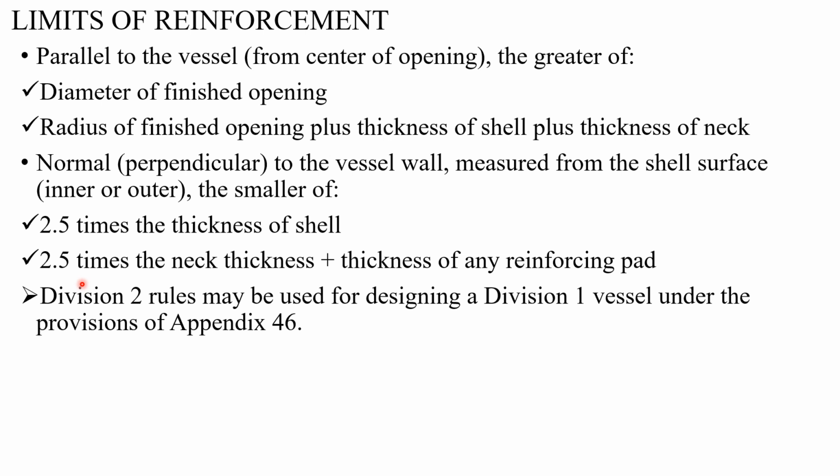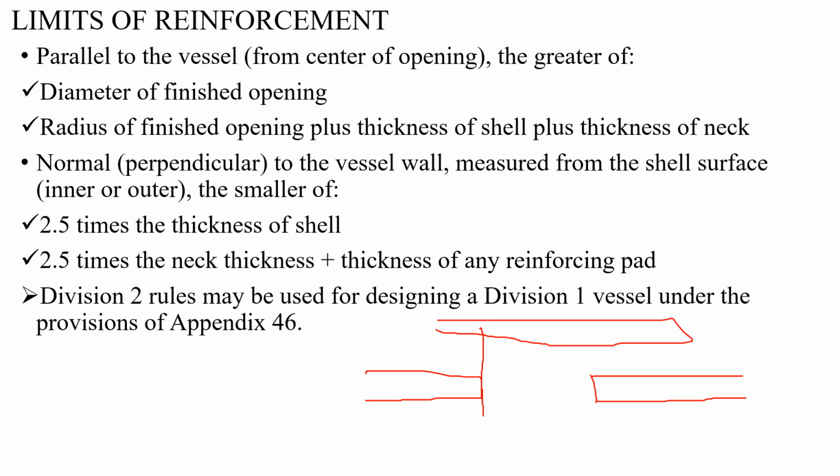There is a limit of reinforcement. So what is the limit of reinforcement? I'll draw and show you. In the previous picture also you can see, for example, this is the shell, and you have a nozzle here. This is the nozzle neck. This is the flange. Sorry, my drawing is not so good. This is the nozzle neck, this is the nozzle going inside, and you want to put a reinforcement pad here. This is the reinforcement pad.